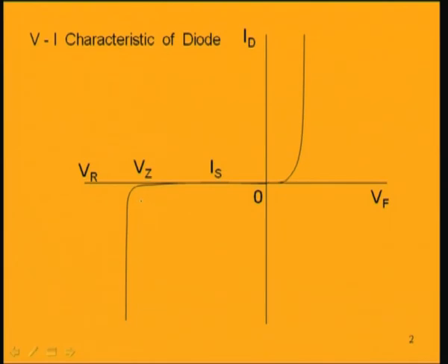But this avalanche breakdown phenomenon generally happens for lightly doped PN diodes. Now, if we increase the doping concentration in P and N type, then we can get the breakdown occurring at an even lower potential. So, if the doping is high, then we could get the breakdown occurring as low as -5 volt. That phenomenon for a heavily doped diode is known as Zener breakdown. Now, there is a fundamental difference between avalanche and Zener breakdown.